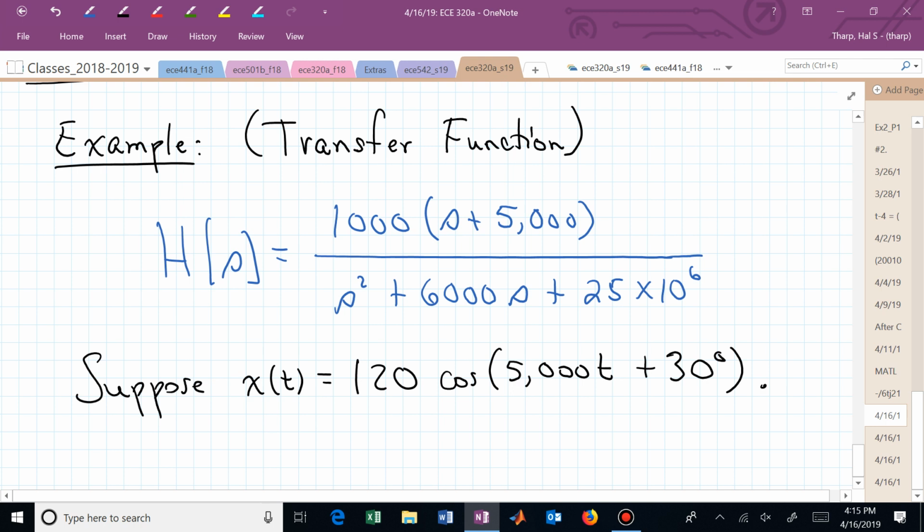And you go, I don't know. I'm going to check each of those 3 quadratics and see if they all have their roots in the left half of the complex plane. If you now have a quadratic, a second order polynomial in s, and it's monic, is this one monic? Yes. So this is monic because this coefficient is 1.